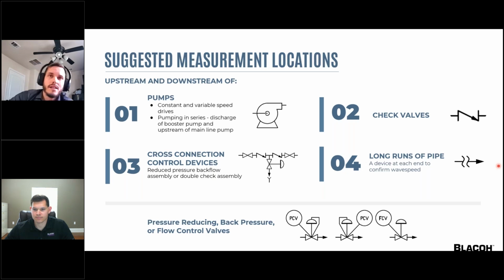breaks. You can use transient pressure monitoring to verify the functionality of and to fine-tune pressure control and flow control valves. Although this list is not exhaustive, it gives you some ideas as to the diverse usage of transient pressure monitoring.